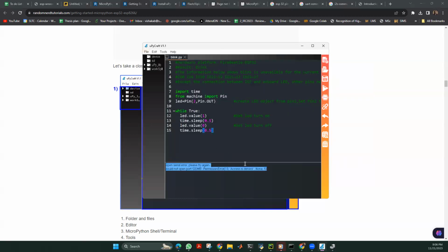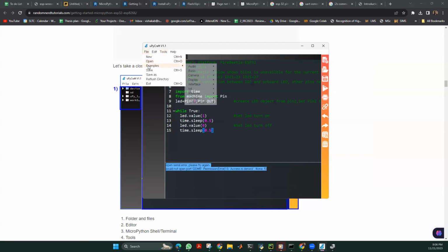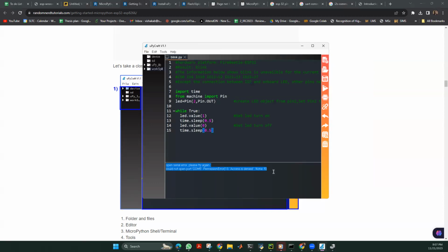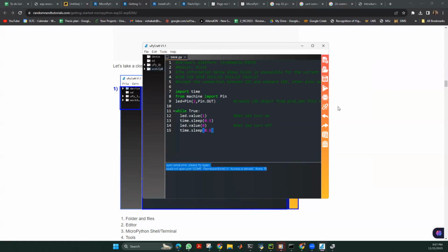We can see whether this is the sample code, right? I'm sure that this is the sample code which I got from file examples, basic, blink. The blink file is the most basic sample code that we can write. Now they are saying the COM5 port is not open or it is not allowing communication. We need to check whether COM5 is available, and whether any other work needs to be done.